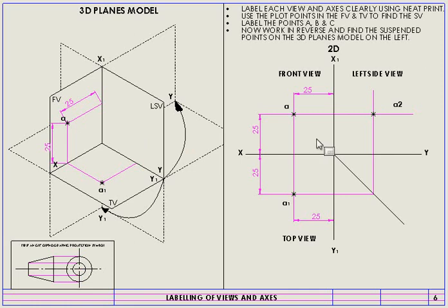Right, the 3 dimensions that I need will be my height, my length, and my width. Now obviously in one view, I only have 2 dimensions at a time. In my front view, I have the height and I have a length. In my left side view, I would typically have that same height, but I would also have a width. Remember, I'm looking at the same object from the left, and I'll be able to see the side view of it, which would obviously give me a little bit more information, which is the width.